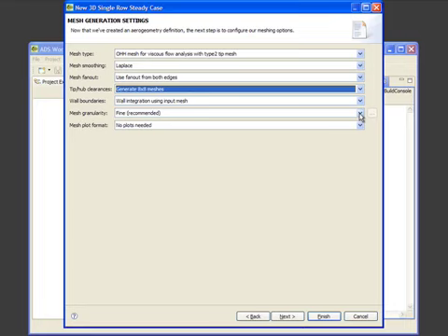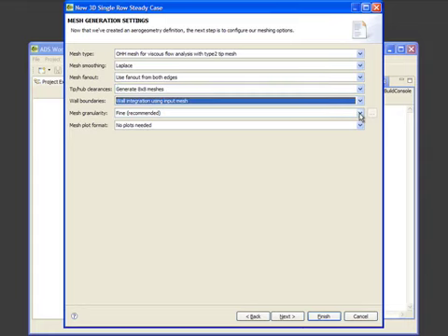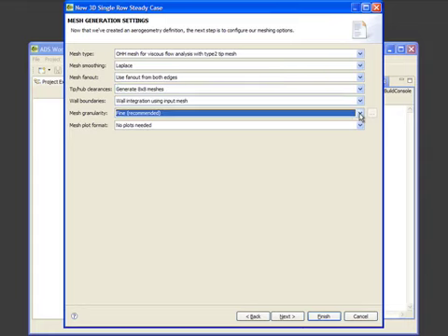The last thing to look at is the mesh granularity. Here it is very important, as it helps to define the number of mesh points between the leading and trailing edge of the airfoil, the number of points from the hub to the tip of the airfoil, the points from the upstream boundary to the leading edge of the airfoil, the trailing edge of the airfoil to the downstream boundary, and then the number of mesh points across the airfoil pitch.